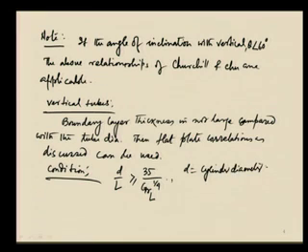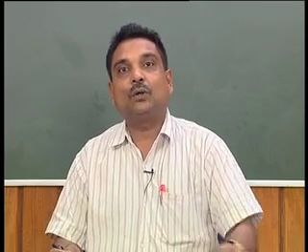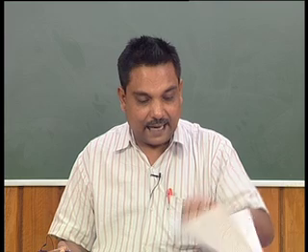So, if the cylinder diameter to length ratio, D/L, is greater than or equal to 35 divided by Grashof based on length to the power 1/4, if that condition is satisfied, then many a time we can treat that vertical tube as a vertical plate.